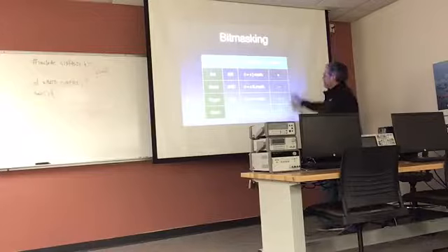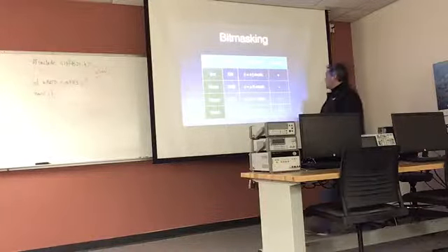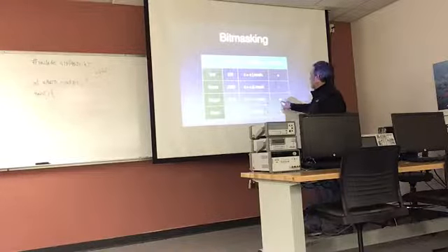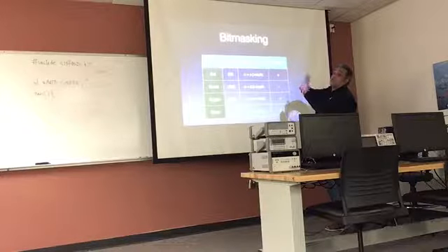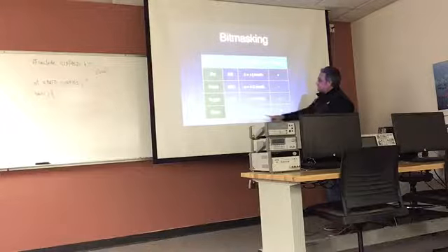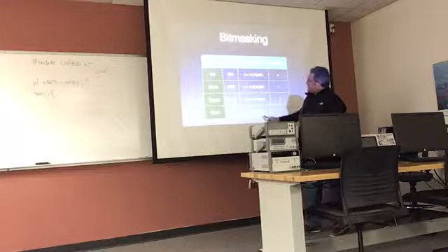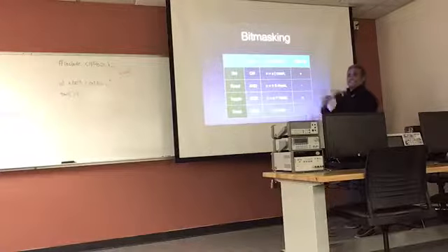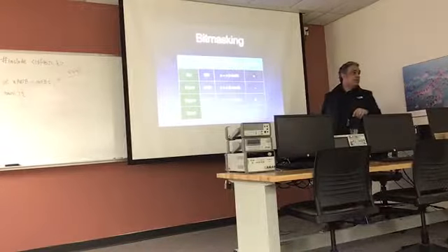I understand set and reset. It's just toggle and read. The toggle is the same thing. The toggle is x equals x exclusive OR the mask, and the positive mask means that a 1 is the one that is going to force the toggle. So that's the idea behind it. And the read, if you notice the difference between the reset and the read, is that there is no save operation. We're exploiting the same gate, but we're not saving the operation back into memory.